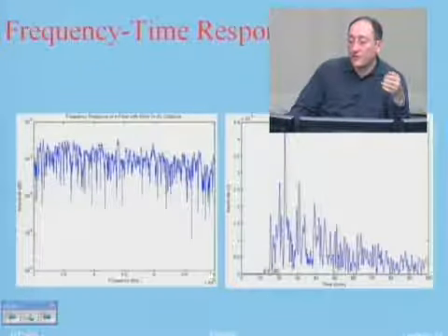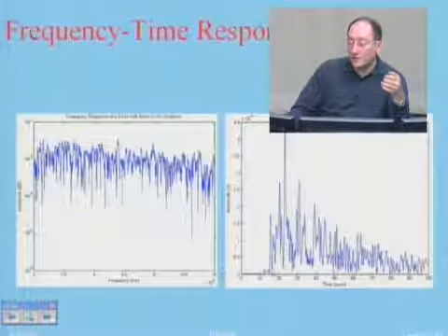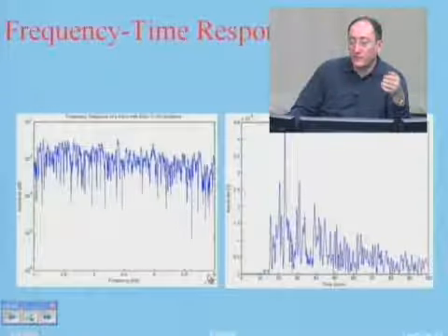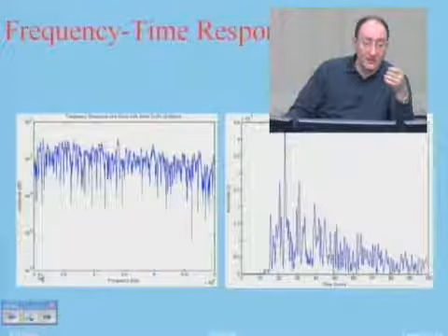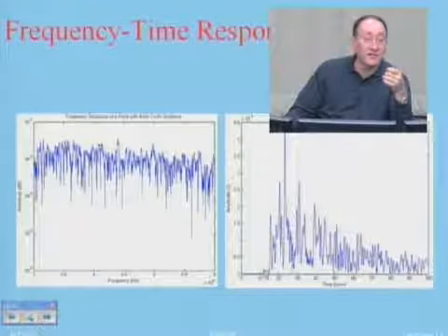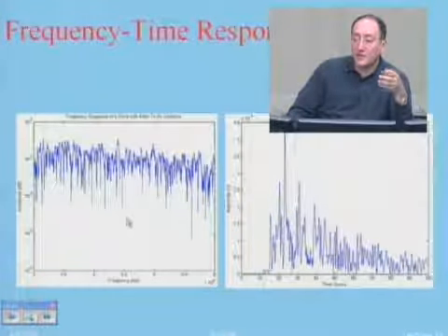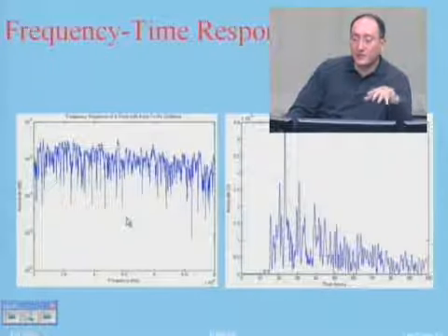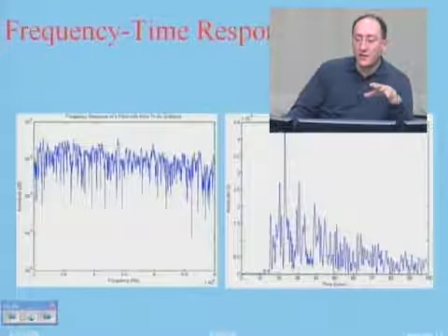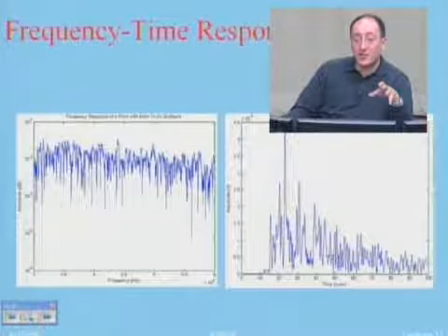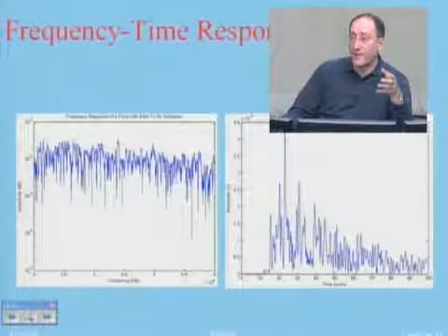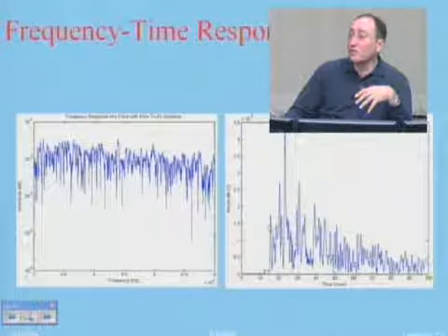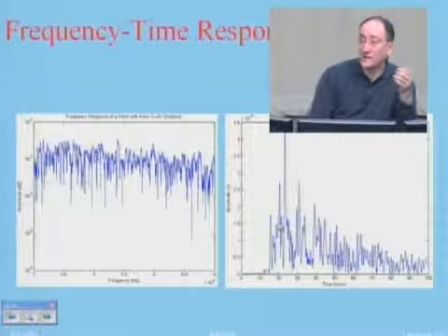So the width of these pulses is like 0.3 nanosecond. Very, very narrow pulses. If you remember in chapter 4, we were talking about wideband measurement systems, which had bandwidths like 200 megahertz. This one has a bandwidth which is 1 order of magnitude more than that.